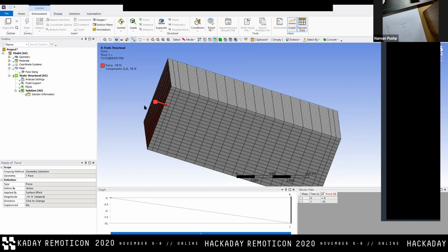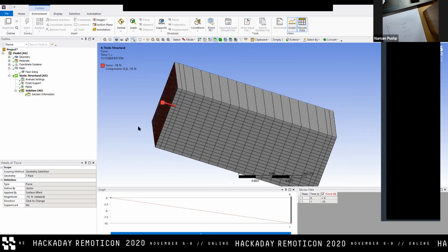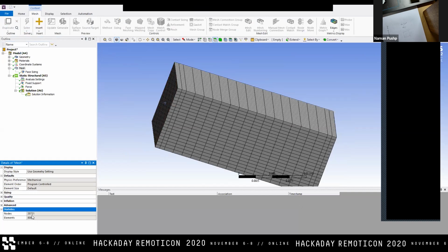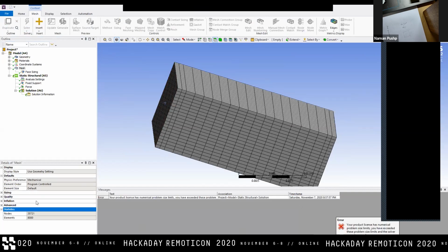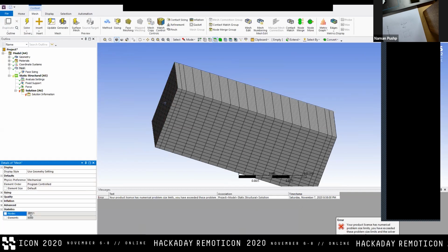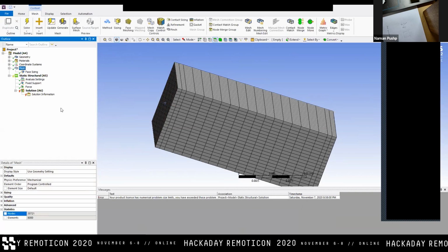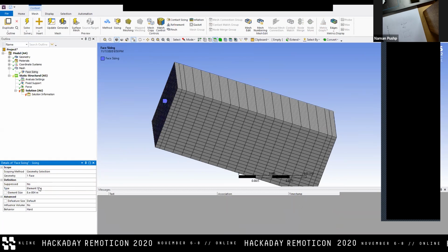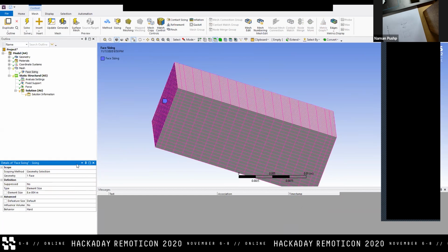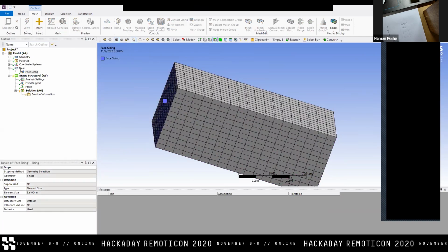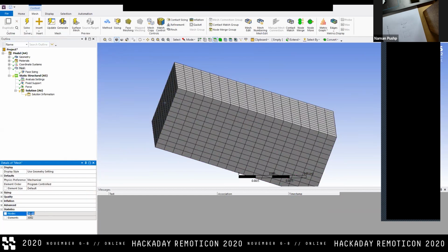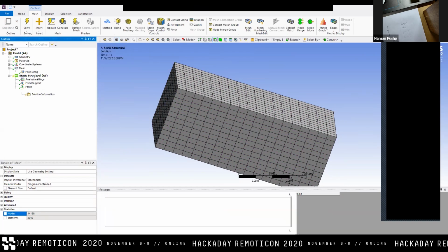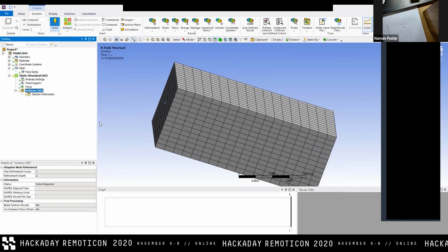So I can actually run a solve, and let's see, hopefully it's not too many minutes. I can actually see how many minutes there are. So we are going into statistics. Oh yeah. So you can see already just with such a simple example, we exceeded the 32,000 limit. So let me just change this sizing so that it can actually run the analysis, regenerate the surface mesh. And now the nodes are much less. This is well below 32,000. So I can actually run the solution.